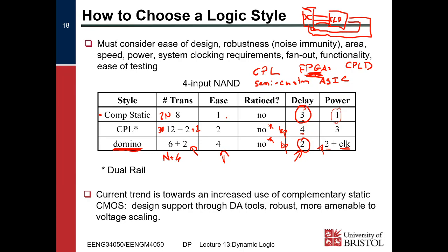The other thing is semi-custom ASICs, where you've got a layer of what you call your logic layer, which would use, say, metal 1 and poly 1 and all the diffusion regions, right?